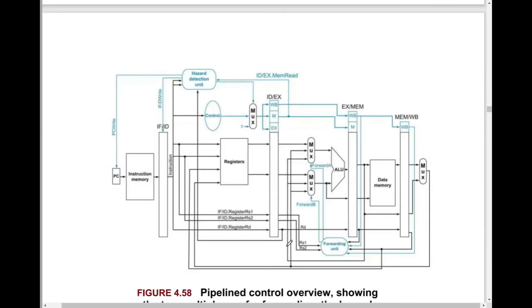So for a stall, with forwarding, you can only forward the data. And if you need to handle a condition like a load immediately followed by an R-type instruction, then you also need a hazard detection unit in the decode phase. In this phase, you can detect the hazard, and the hazard detection logic is similar to the way I explained the logic of forwarding. In a similar way, you can find out the hazard detection logic.